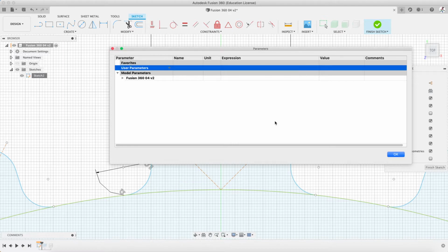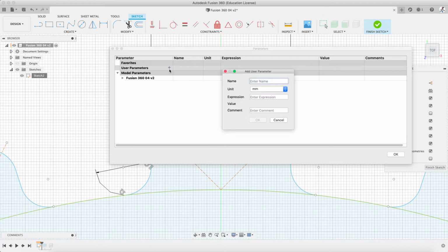So when you make parameters, what you're doing is creating basically a list of numbers, a list of units, and those are named exactly what you would like to name them. It's really important to make sure that you have the same naming conventions going forward. Whatever you choose to use as a name structure, it's good to pick something that you can memorize pretty easily. Myself, I use a coding name structure because I have a little bit of a background with coding and programming as well. It helps me really visualize what I need, because if I think of something and how it works with code, then I can see that exact parameter come out right away, just the way it's designed. So we are going to use no spaces at all.